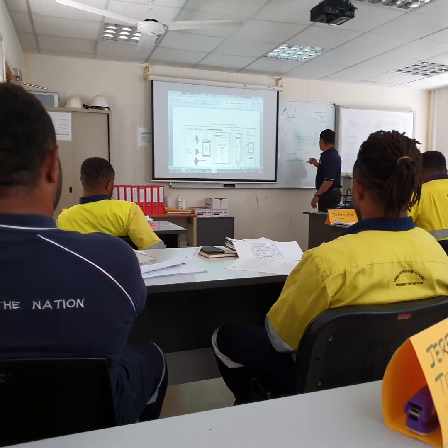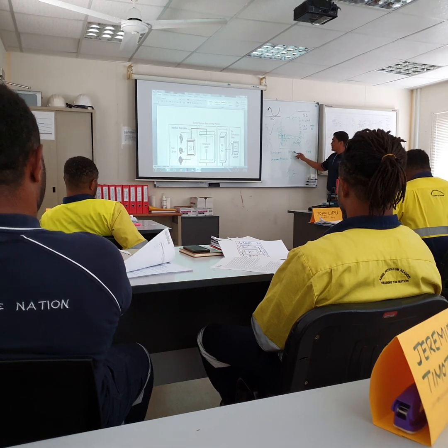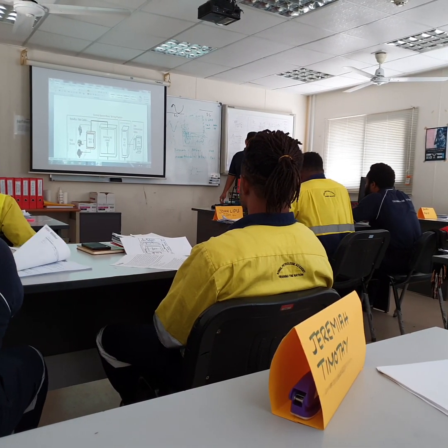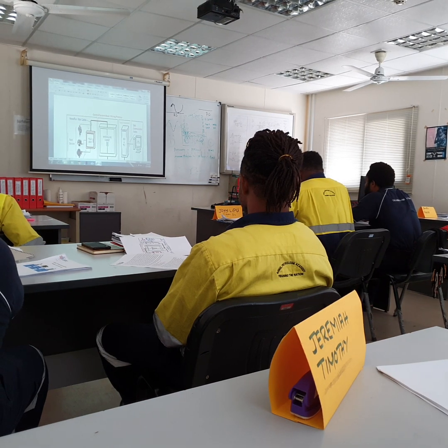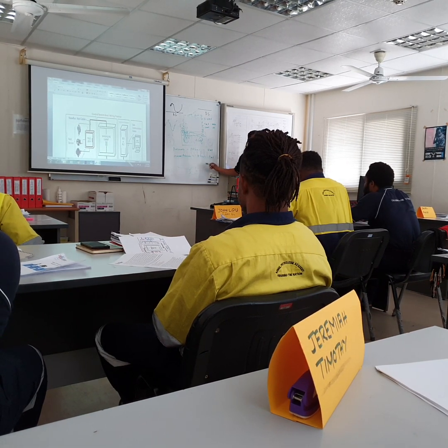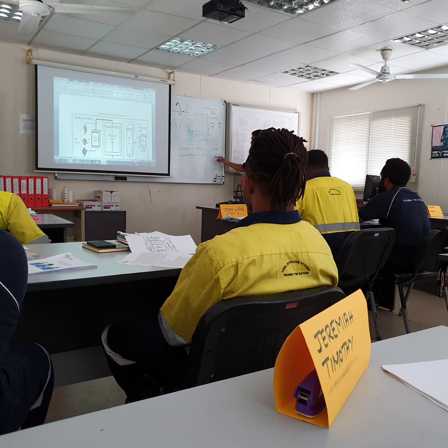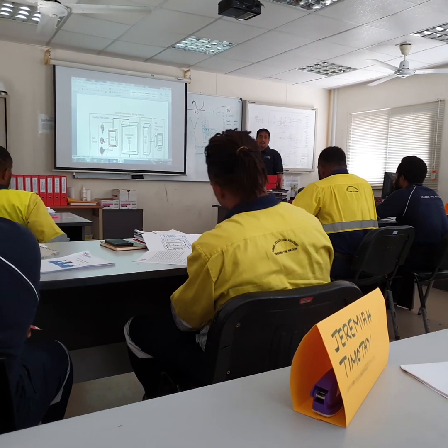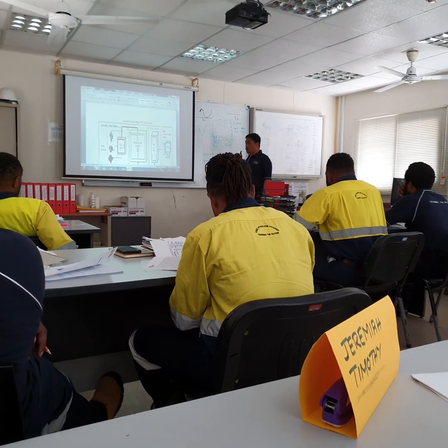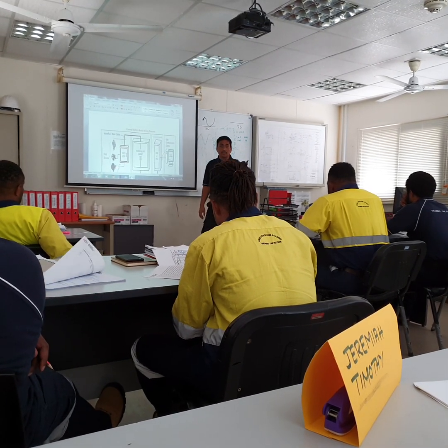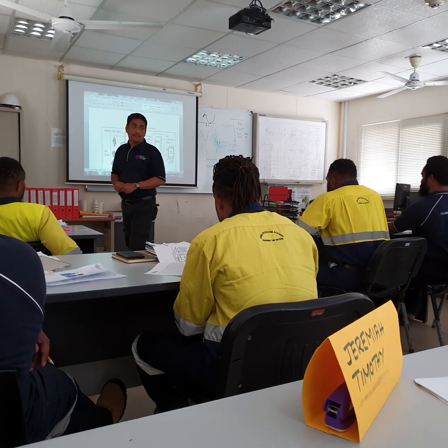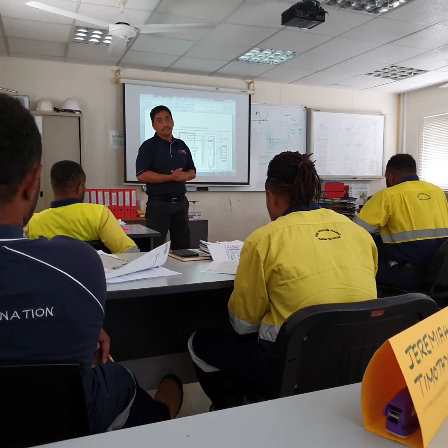So this is your signal, representing the value of pressure. If you measure it, you will get either 4 milliamps or 20 milliamps for the 100 bar. You are going to connect the meter in series, or sometimes you have a calibrator that will measure that, right?